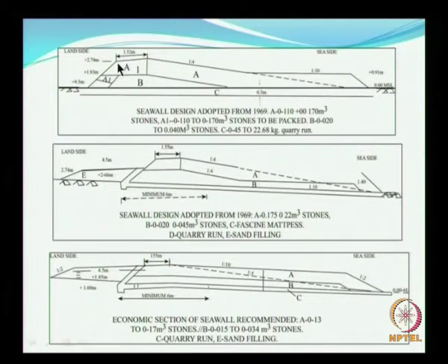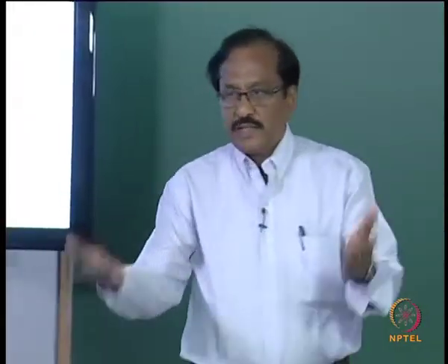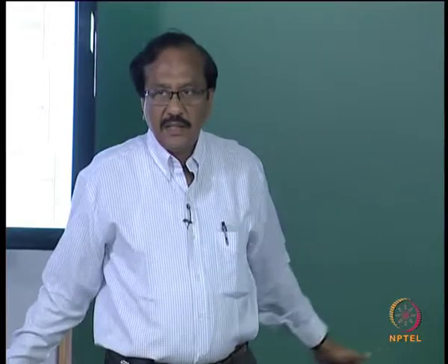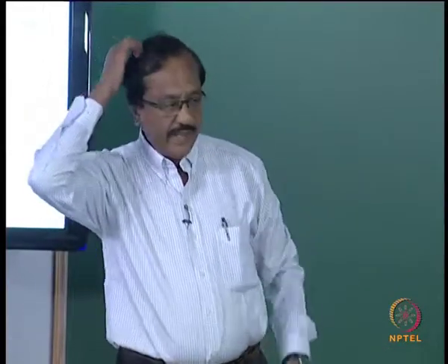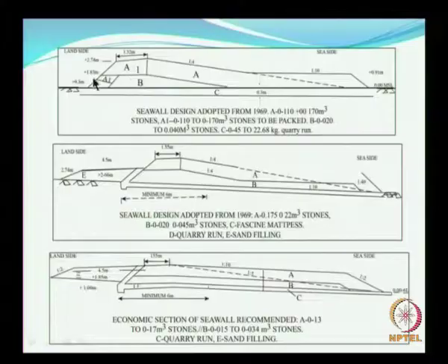This is all right under normal circumstances, but in the event of a coastal hazard, when there is a storm, the whole water level will go up, and then there can be some amount of overtopping. If the waves are overtopping, then there can be a down rush, and when there is strong percolation here, the whole thing can penetrate here.